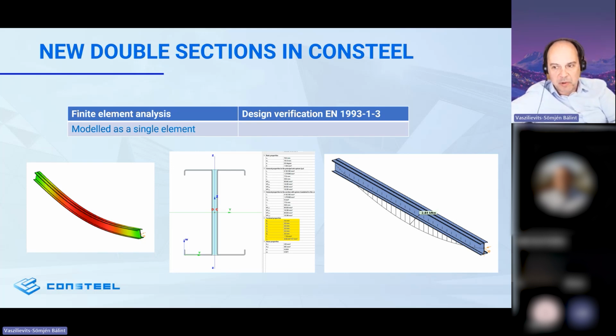And if we just remember that Eurocode wants us to always consider the effect of a possible shift of the effective cross-section, at those locations where the two sections are not connected to each other, the two sections can displace relative to each other, and therefore one can assume that once an effective cross-section is formed, due to the eccentricity of the effective cross-section compared to the gross section, a bending moment can also be formed.